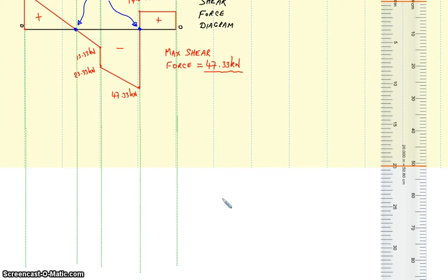Before we can actually draw our bending moment diagram, we will have to calculate our bending moments. So initially, to start with, I'm going to draw again a horizontal single line, and at each end of that I'm going to put in a 0, because again this horizontal line represents a line of zero bending within our diagram and does not represent the actual line of the beam itself. So we need to keep that in mind whilst we're doing that.